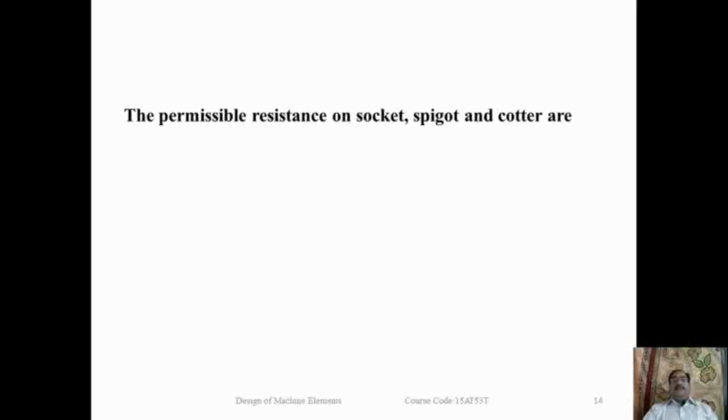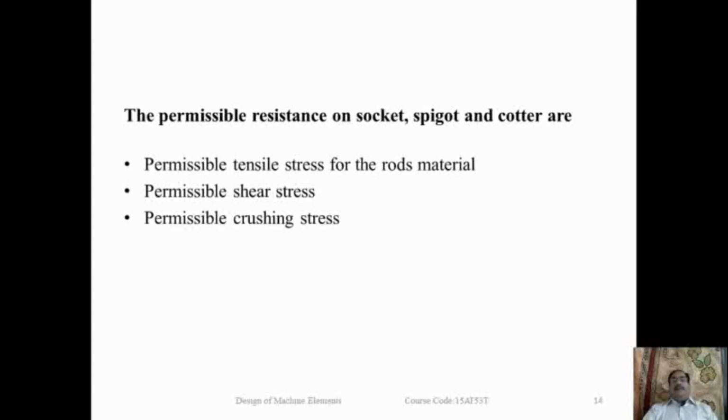The permissible resistances on the socket, spigot and cotter are the permissible tensile stress for the rod material, permissible shear stress, and permissible crushing stress. For all these stresses, the units are either megapascal or Newton per mm square.